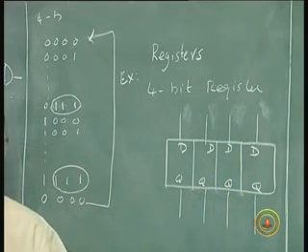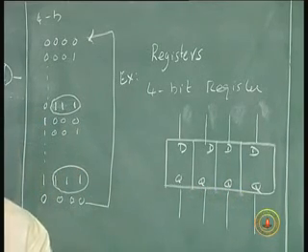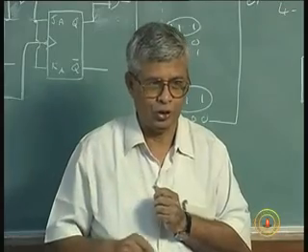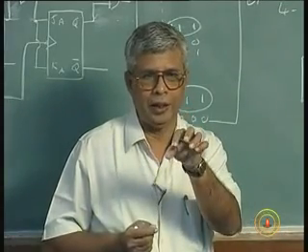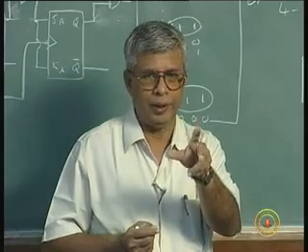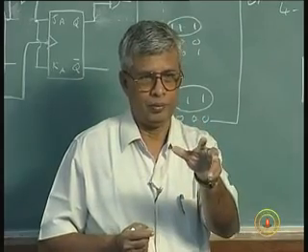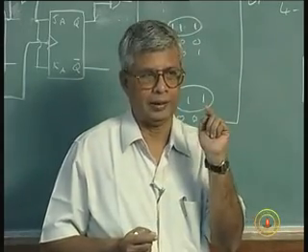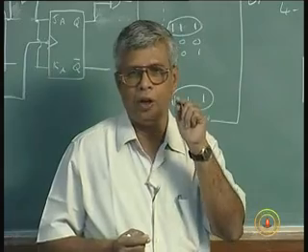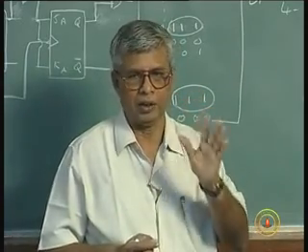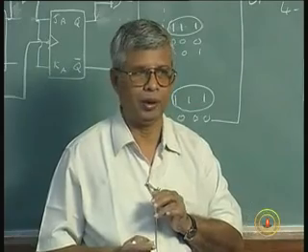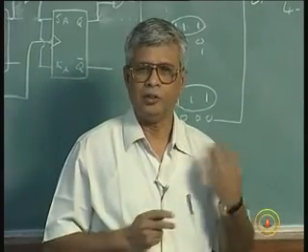Normally these flip-flops can be controlled by a single clock. Internally that will be connected, of course. As I said, externally when you are looking at a device with 4 bits, as a user you have only one clock to connect, one power supply to connect. So all these flip-flops need VCC and ground, or VDD and ground, whatever is the nomenclature for the supply voltage. All those things we are not showing.